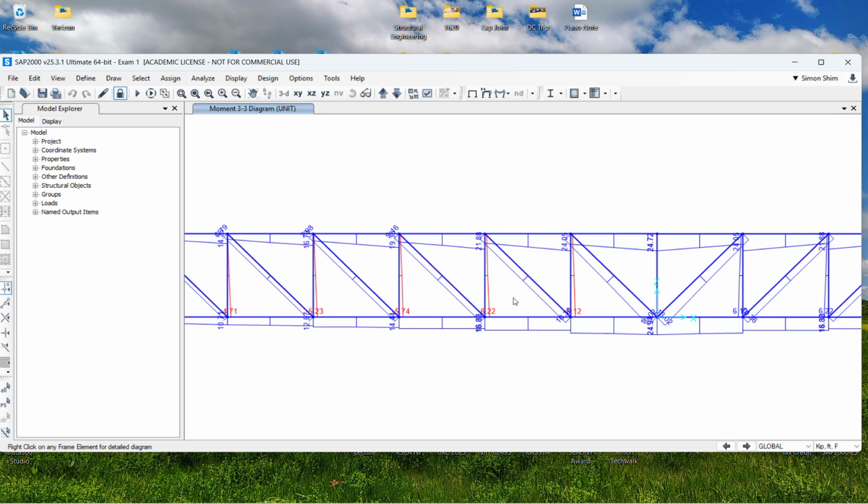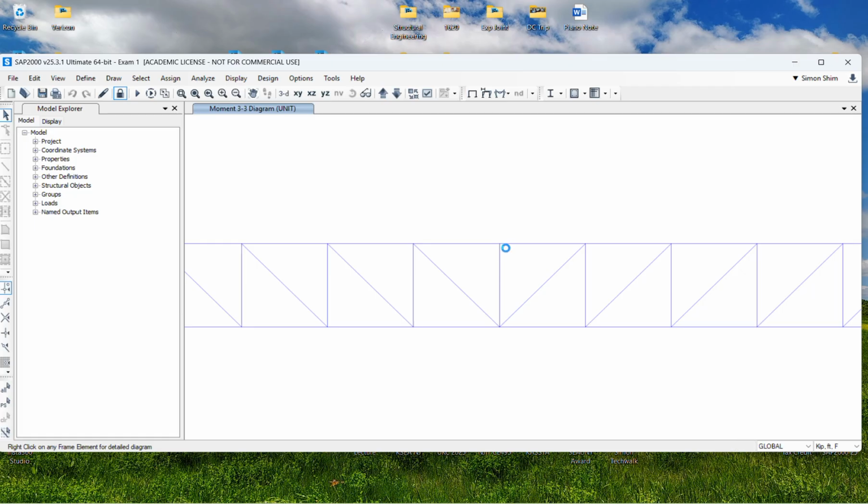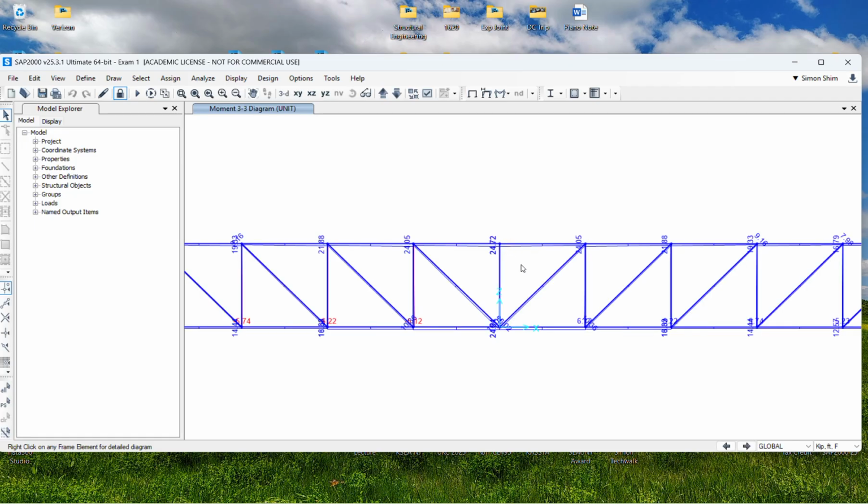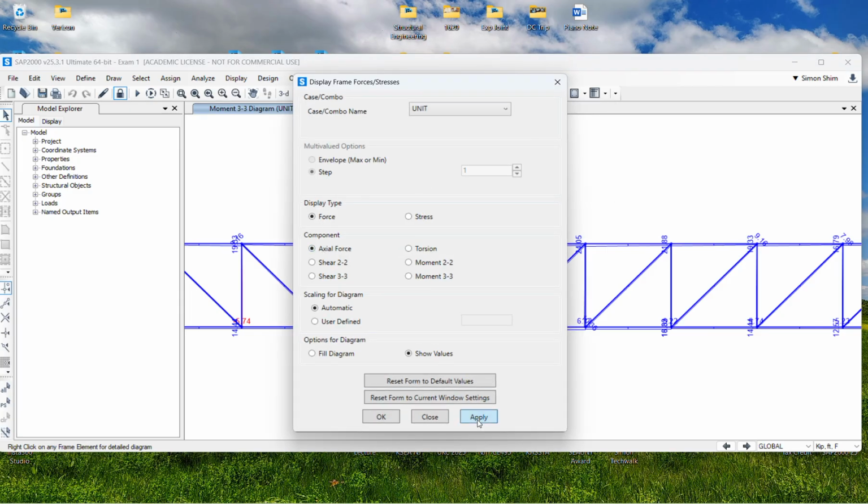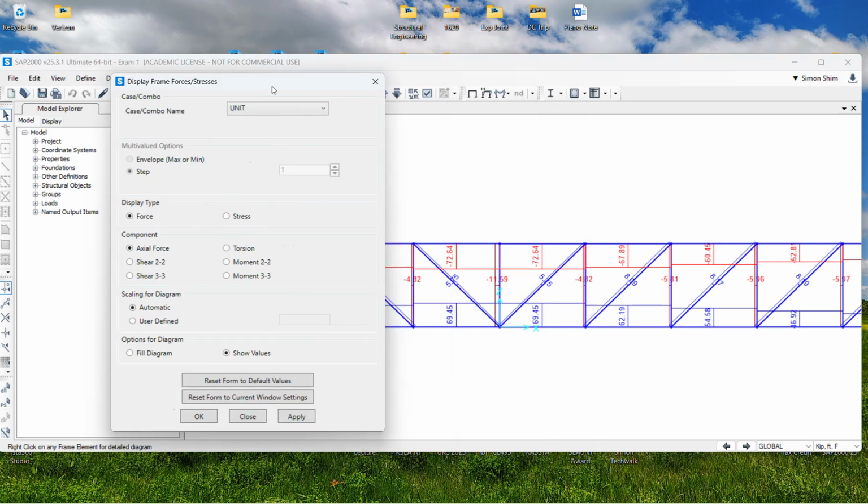Because of the truss configuration, the primary force is not going to be a moment, it's going to be the axial force. I just explained that when you have wind pushing you, your two legs are going to experience compression and tension. Basically, wind is blowing your body and generating overturning moment. But since we have two legs connected by the body, which here is the top and bottom chord tied with the vertical and diagonal members, all the moment will be decomposed into the axial force, right? So truss is primarily taking the axial force.